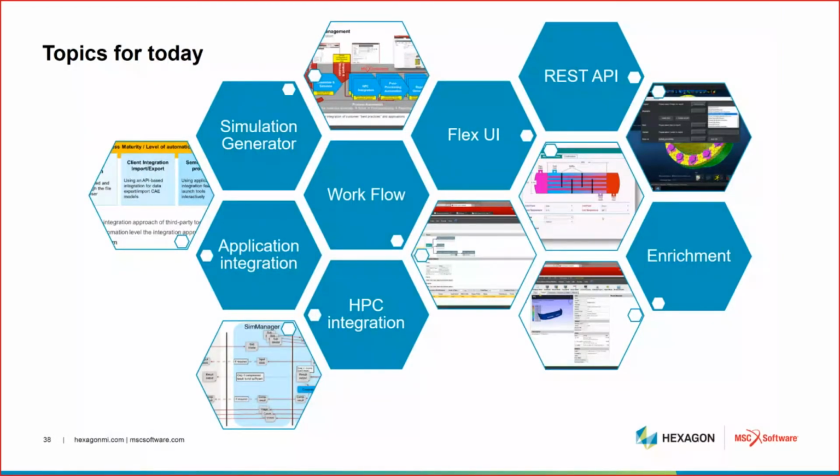But in this instance, you can choose whatever approach you like on that particular analysis environment. If you want to create a new variant, we can then say, well, let's take this assembly as a baseline for the initial analysis. And then if, let's say, your loads have changed, or maybe you want to look at a new wing structure slotted into that particular assembly, you can create a new subvariant of that and then reanalyze that particular process to go from there. Okay, so that's the summary of the topics that we had for today's primary session.